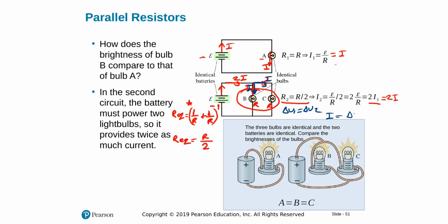And then finding the current, I is equal to delta V over R from the general equation. If the resistance is larger, it gets the lower current as we discussed. If they have the same resistances, as in this case, then they will have the same current. So they will share equally here. Therefore, I have current I here.